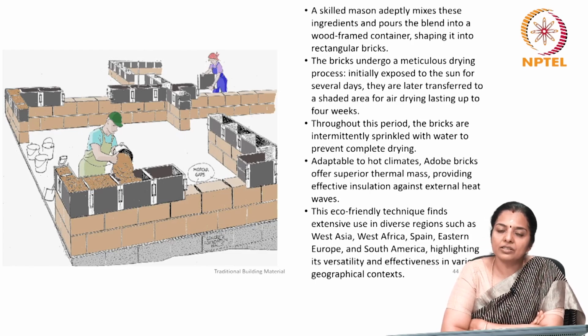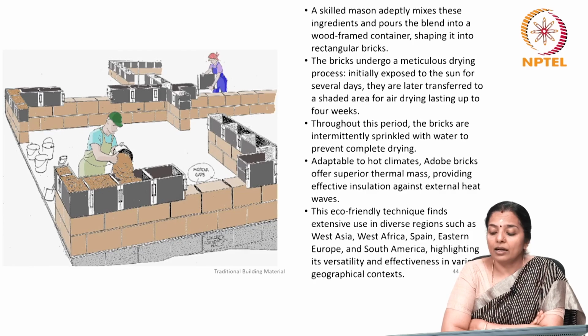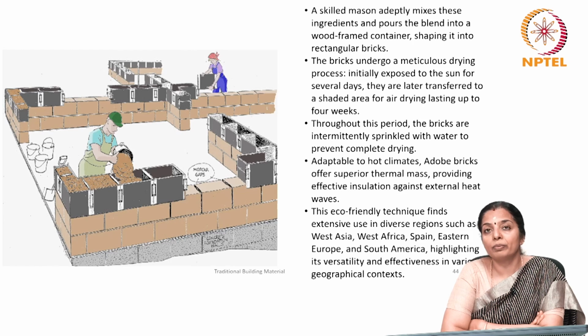Then you have to transfer this to a shaded area for air drying, which can last up to even 4 weeks. During this entire 4 weeks period, the bricks must be intermittently sprinkled with water to prevent complete drying, because the curing is not yet complete.